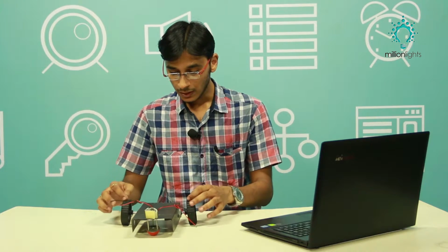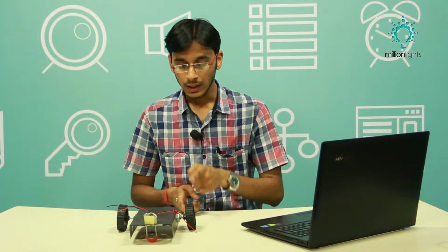Just one thing that we have to follow is that we have to check the connections, and from Arduino we have to write the program which will give instructions to the L293D to move it forward or backward. Now when we are making it go forward, if you want to stop this robot, then you have to take care that simultaneously to the left motor and right motor we are sending the instructions of low low or high high, meaning both the pins are connected to ground, and this also. So all four pins should go to ground, or all four pins should go to plus 5 volts. They should be done simultaneously, because if we don't do that, there might be an error.